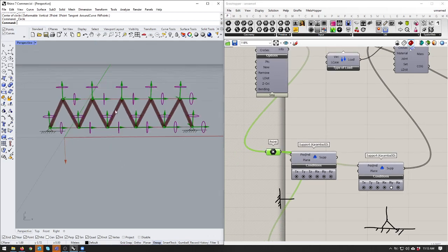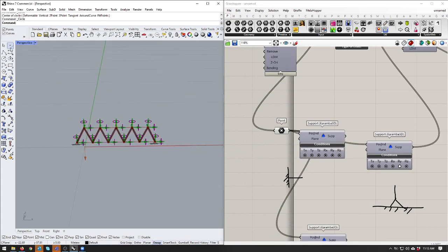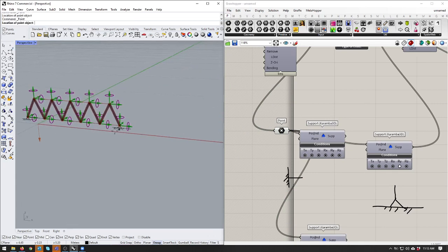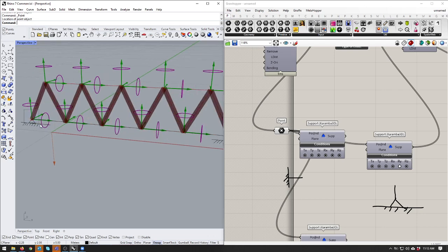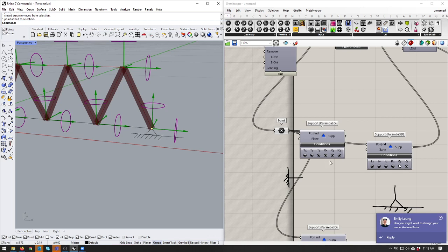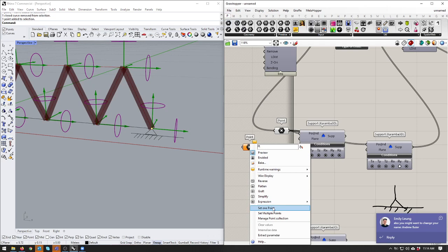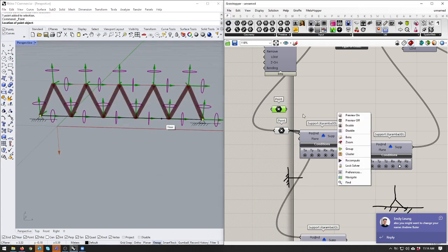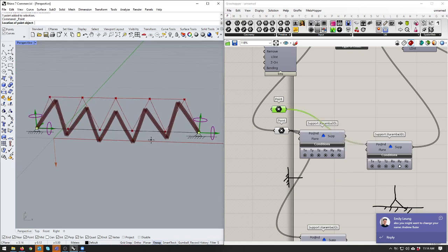Generally what I find is important is if you place a point in the model, we should be using these points as our support points rather than picking points out of our model. And I'm going to get into why this is going to be a problem in a moment. So these 2 points, if I chuck them in now, look, we're going to start seeing that deformation happening on those zigzags, because now there's only supports on the ends rather than at every point in that truss.